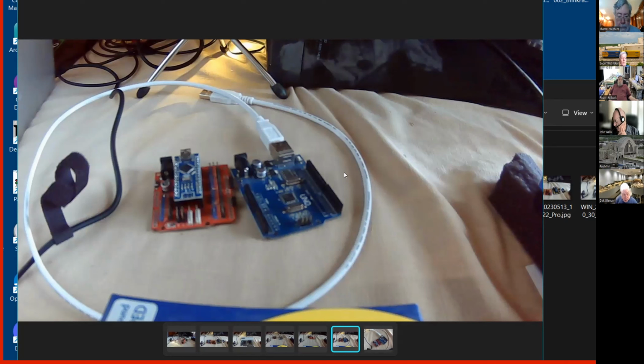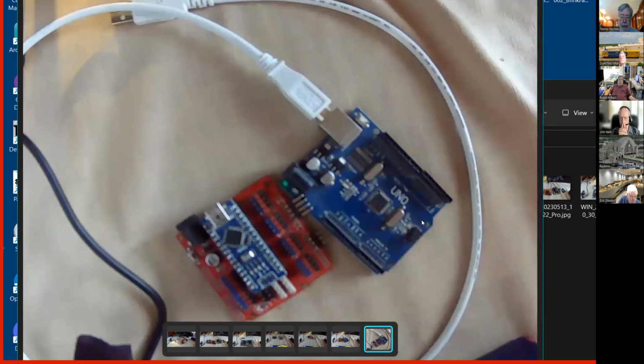I would say from working with the I2C stuff that if you're using some of the I2C boards, they need to be right next to the Arduino, not very long. I had a long cable on the original ones I did, and it was kind of flaky every now and then, which is why I went to using an Arduino on each end. The Arduino on the left there with the blue and the red, I can order that part in bulk on eBay for about $3 or $4.